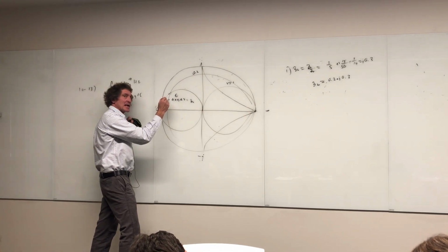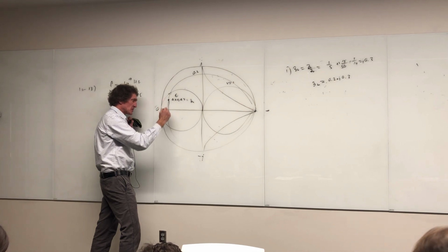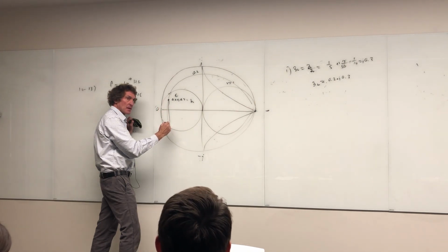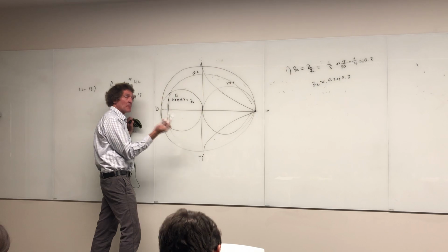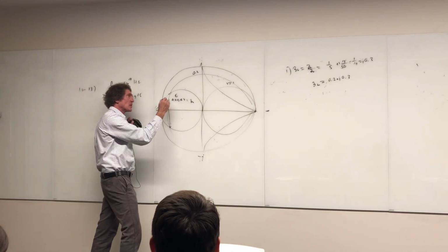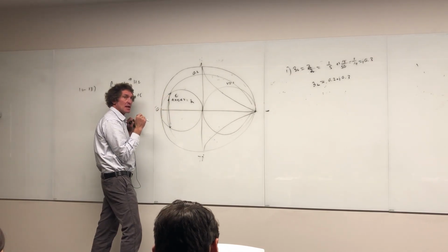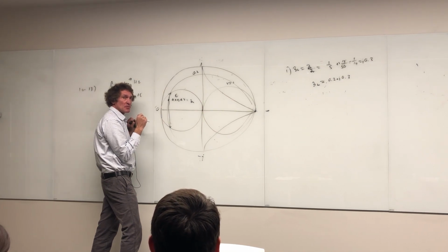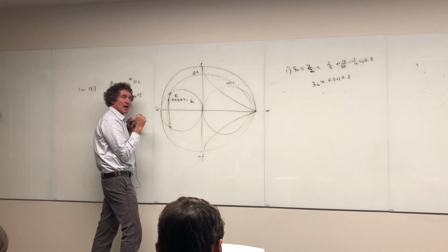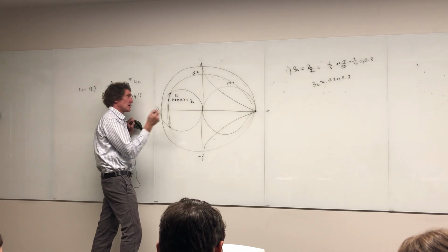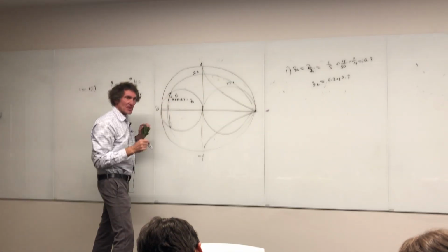If we add negative impedance, which would be a capacitor, we'd move down here, correct? Remember, a minus j would move it this way, or we could add an inductor and move it this way. You got a preference? Either one will do. You want to move up or down? You want to get an inductor? All right, that's fine. We're going to use an inductor.